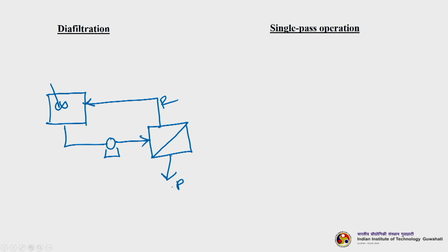Okay. So, what is happening actually, we can separate solutes also here, two solutes. However, what is happening in diafiltration is that the solvent, okay, is getting reduced. So, solvent is getting reduced here, right. So, we need to add buffer. So, we add actually buffer here. Okay. So, it is called diafiltration buffer. Usually it is nothing but a solvent only, right.